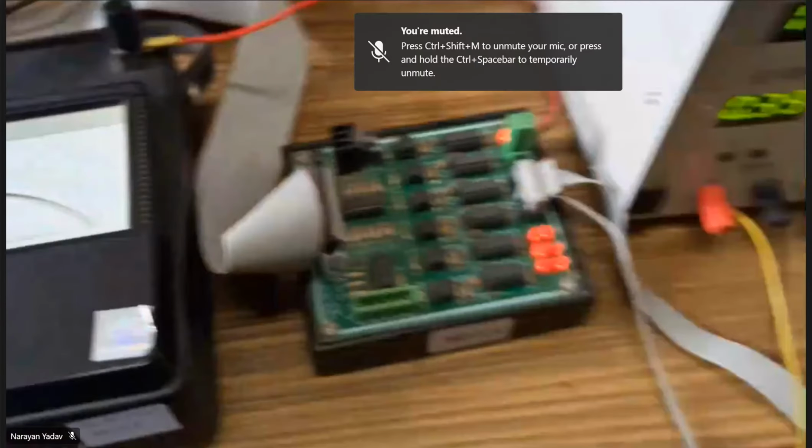The output data is the output voltage is 49.6 volts. The output current is 112.2 milliamperes. The fundamental component of output voltage is 49.5 volts and THD is 1.8%. Now we will change the load again.